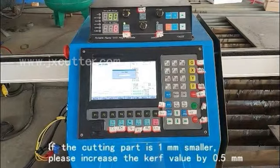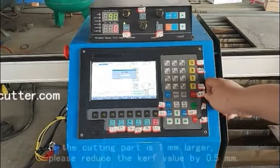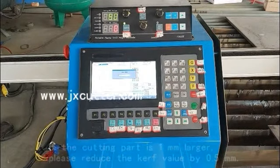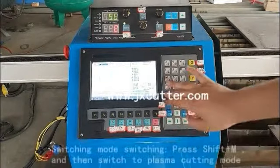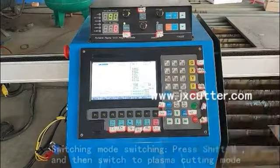If the cutting part is 1 mm smaller, please increase the curve value by 0.5 mm. If the cutting part is 1 mm larger, please reduce the curve value by 0.5 mm. For switching modes, press Shift M, and then switch to plasma cutting mode.